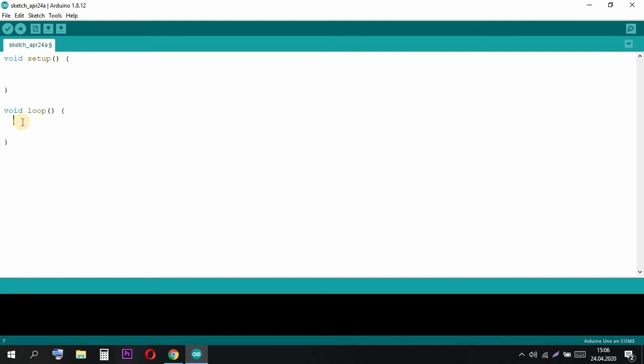You have connected a temperature sensor in the pin number 5, and you get this, and in the loop you say take this information and according to information, if it was, for instance, 20 degrees, make it turn on the radiator or something like that. You can write in the loop, so it will just repeatedly go and check if the temperature is below 20 or no, and if it is below 20 it will just turn on the radiator. So that's like this.